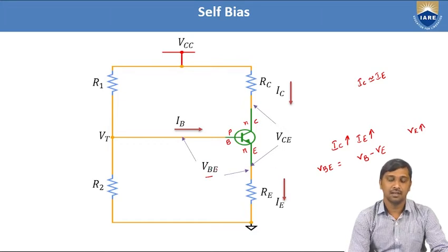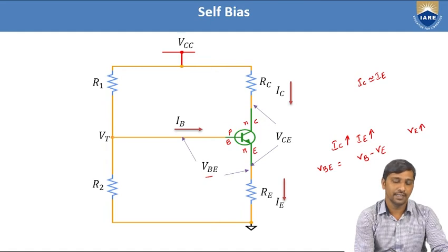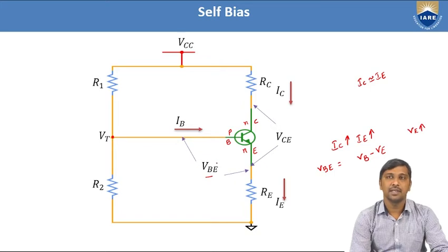To compensate for this, or to keep the emitter base junction always forward biased, we use a potential divider network voltage. This VT drop keeps the emitter base junction forward biased even though the voltage drop across the emitter changes. Whatever the voltage drop increases by should be compensated through this potential divider network voltage, to stabilize a constant collector current at the output of this transistor.